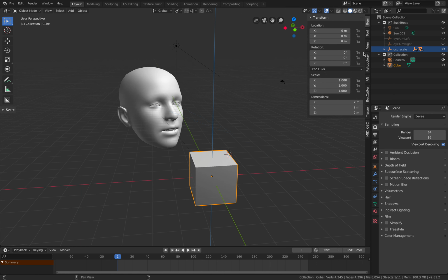And then this is the panel for properties, and it's got a lot of things, but normally you have items, and items give you the information about the location, the position of what I'm selecting, the cube, and rotation and scale. So you can scale this cube in X, Y, Z. You can see the dimensions as well, but it's a local scale value. You can select all of them and make them back to 1, 1, 1, or you can try moving this thing around using the numbers, but normally in Blender you like to use hotkeys.